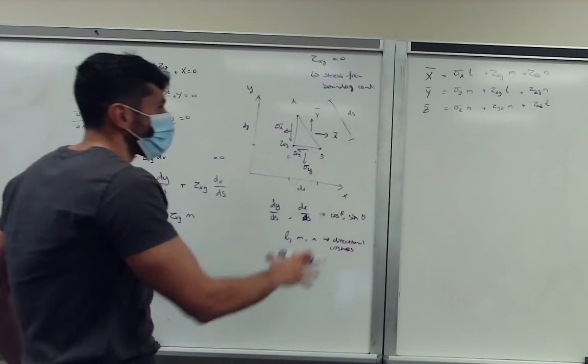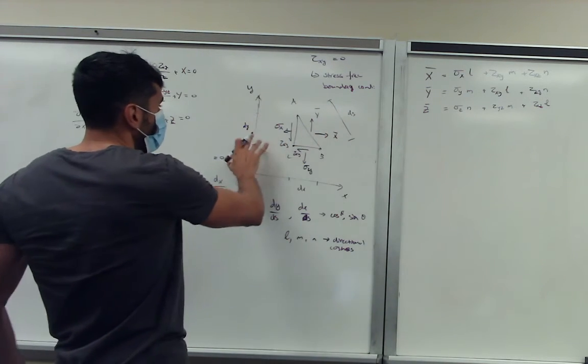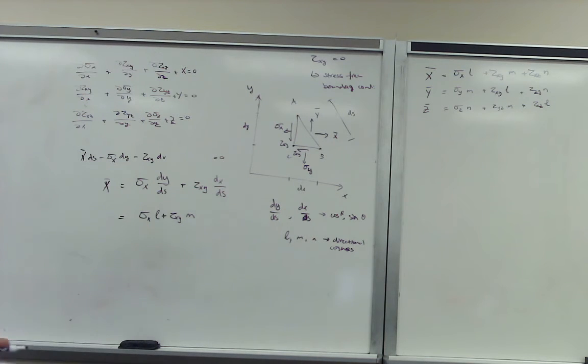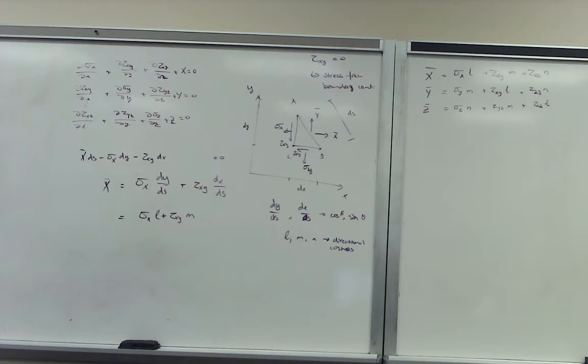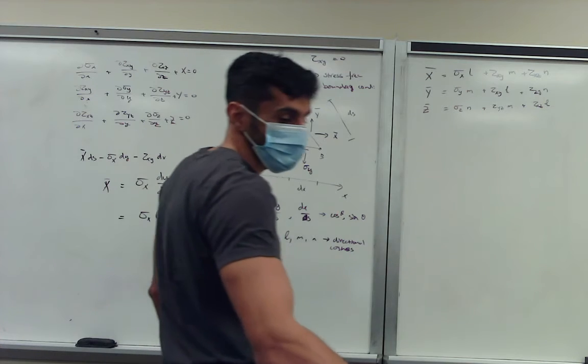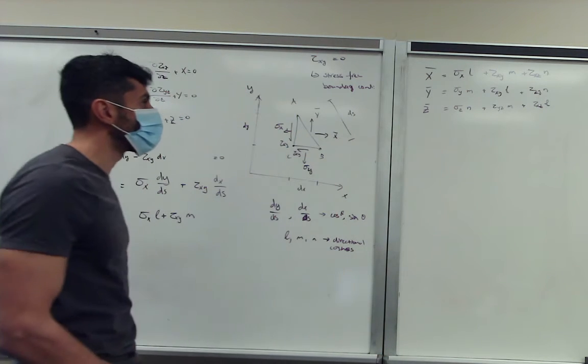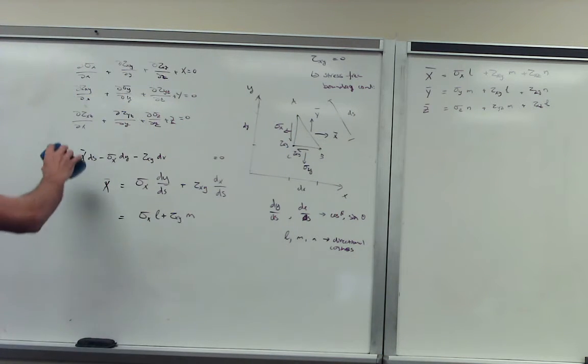So this basically corresponds, if we take this element and look into an x, y, and z coordinate system, and we derive the same equilibrium equation for a 3D case. In this case, this was a simplified 2D case. We get those terms, we get those body forces as part of the stresses in x, y, and z, and corresponding directional cosines.